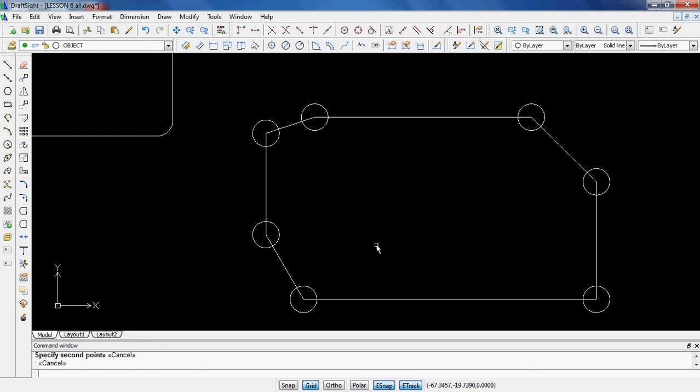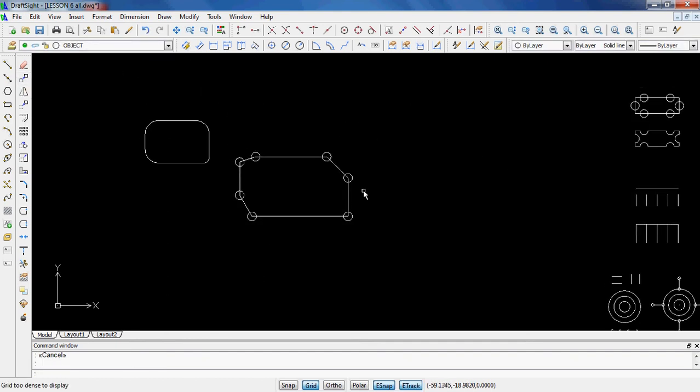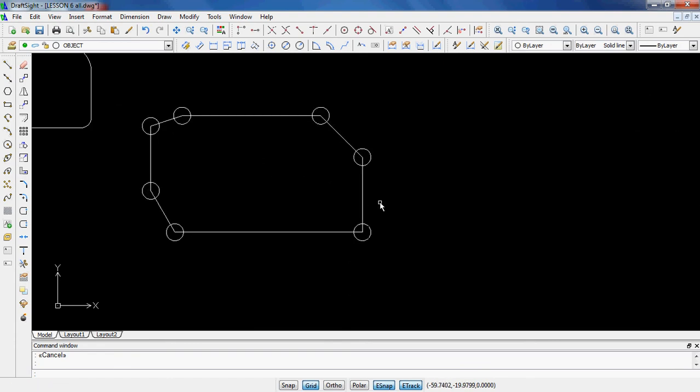Obviously, when you look at 7B and you see all the different circles that you need to move around, this would definitely be the way that you want to do it, because it would take you much longer using Control C and Control V. So understand the usefulness of using this version of copy on the modified toolbar. Moving on to 7E, we get into the mirror command. The mirror command is a very cool command because it makes things a lot easier.